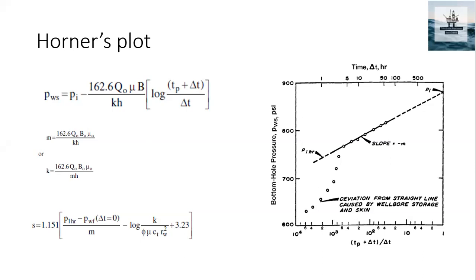So when delta T is equal to 0, TP will be ending at that particular point, and the pressure is expected to be minimum when delta T is 0. That means the pressure corresponding to PW, not PI. PI always will be constant, but PW at delta T equal to 0 represents that shut-in is about to start. It hasn't started.